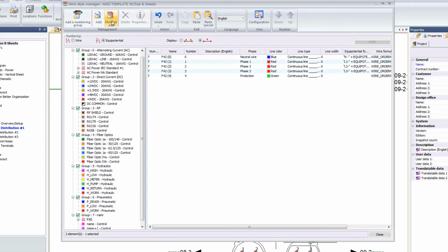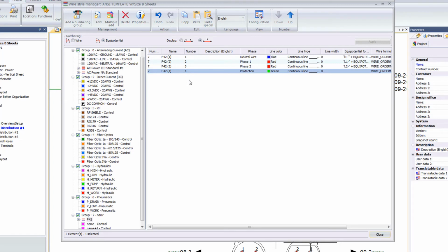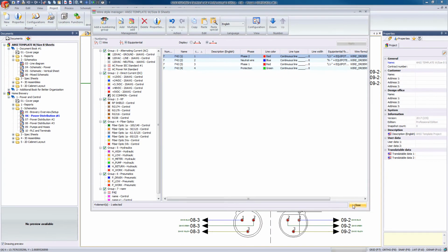We also have the option to create a multi-wire style. By default, a multi-wire style creates 5 individual wire styles. You can add or remove any of these wires as necessary and edit each wire in the same manner as we previously demonstrated. Once all the wire information is filled in, we have the option to reorder the wires. This will affect how the wires are drawn within our schematics.